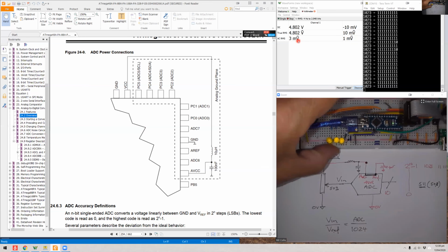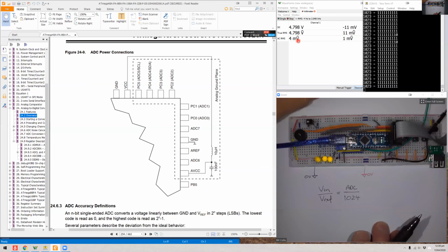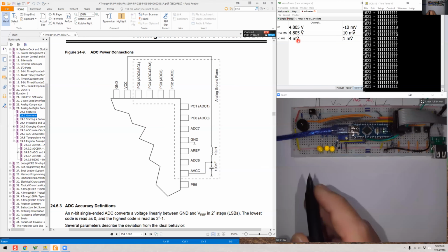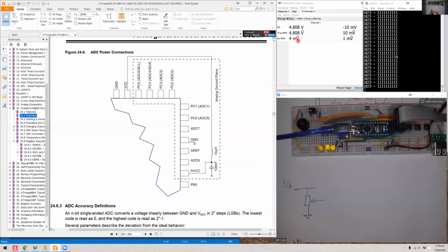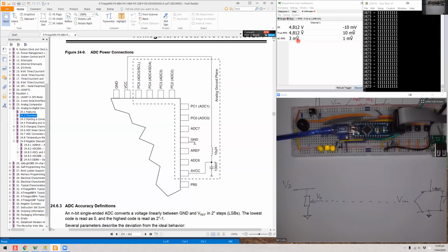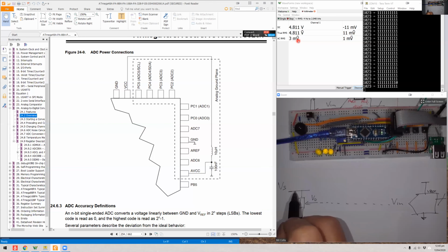If, for instance, you're going to use your microcontroller with some sort of sensor, whatever it may be, and we've got a power supply for the sensor and an output voltage connecting to the V-in of our ADC, and we've got our V reference voltage here, then if this voltage varies, this varies, but this voltage reference hasn't varied.